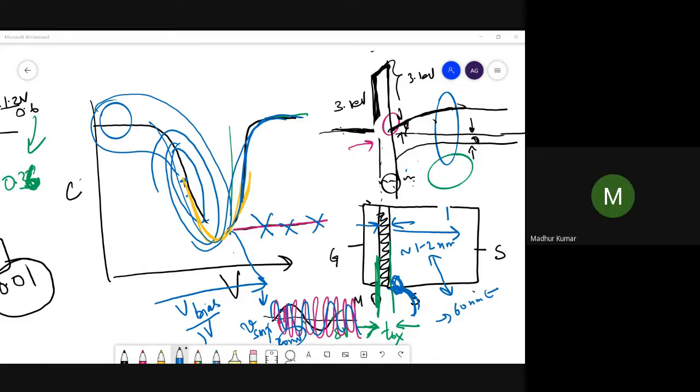And additionally, when an external electric field is applied, then also, because at some point, if we apply reverse electric field, bands also become flattened, right? So we do have to give a reason that because of external electric field also, we need to satisfy. But we have not talked about external electric field yet, we are still talking about internal electric field. When there is no voltage applied to gate or body and you apply voltage, band bending would change, but yes, it's okay.